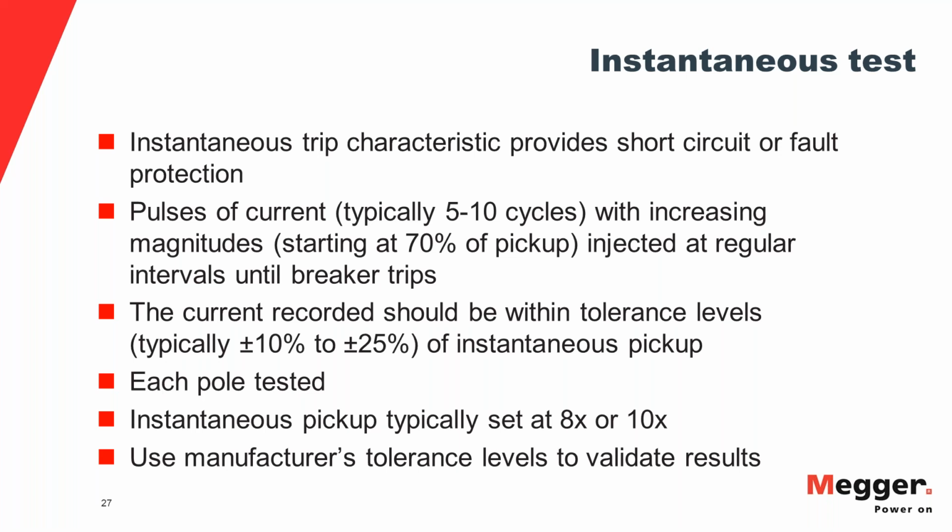Each pole needs to be tested separately. The pickup values for instantaneous tripping are set the highest. They're typically either 8 times or 10 times.